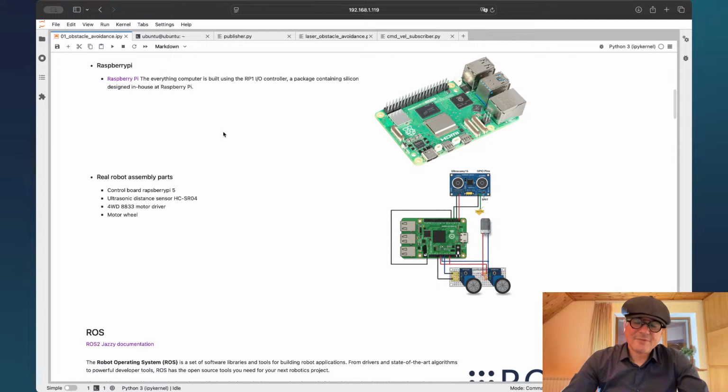Can you hear me? Yeah. About the example that you mentioned, the simple algorithm. I understand this is just the simplest possible algorithm, but even with it, it's super easy to get the robot stuck in a room, because it cannot pass tunnel-like obstacles. It will spin endlessly, always seeing the obstacles, right? Yeah. Because it's spinning in one direction, it should also spin in the opposite direction from time to time.